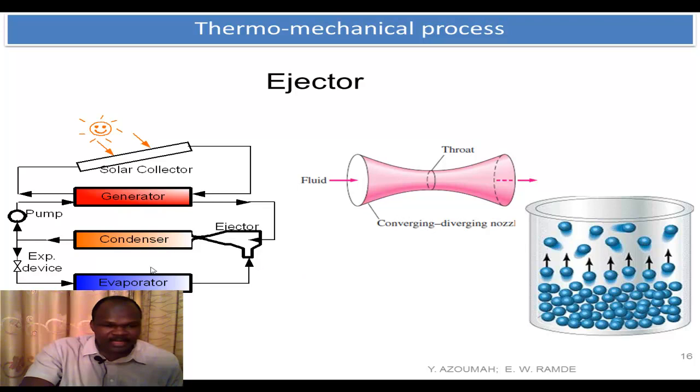This is being used for cooling, but in industry, ejector is also used for drying products, soap, and other products. The food industry. So imagine you have your food and you want to take some vapor away from your food, some moisture away. You want to dry it. Just have an ejector, have some steam go through it. It will entrain the vapor away, and then you get whatever gotten dried.